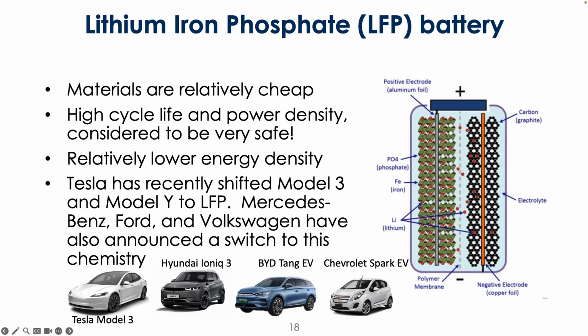And so the use of LFPs has been really touted as the types of batteries where you could be fast charging your car all the time and you would basically see no degradation. You could be charging your battery up a lot fuller and see much less degradation. So from a cycle life and stability perspective, LFPs are quite good. The one area where they're maybe lacking a little bit more is energy density. So you've got to pack more LFPs to get the same amount of range in your vehicles. So there is that sort of trade-off.